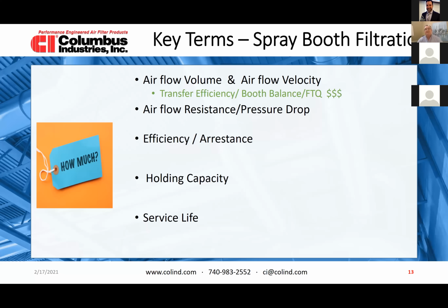So the booth needs to be balanced. The transfer efficiency costs money. You need to stick as much as possible to the level that you're supposed to be at. And the first time quality does cost dollars. If your booth is unbalanced, you have particles and turbulence all over the place, you're going to have some defects.